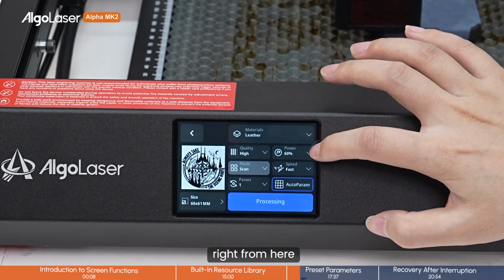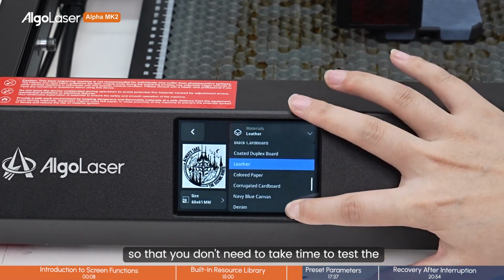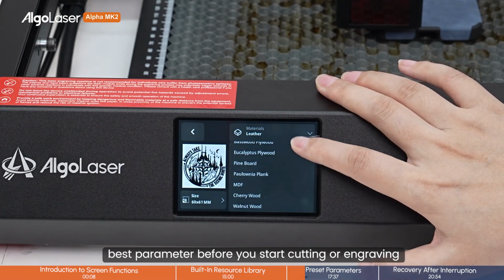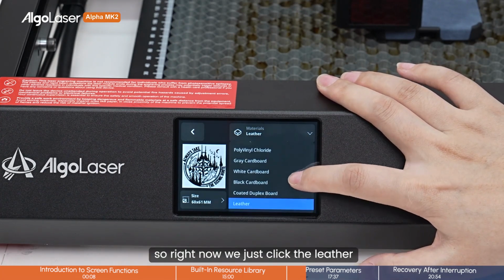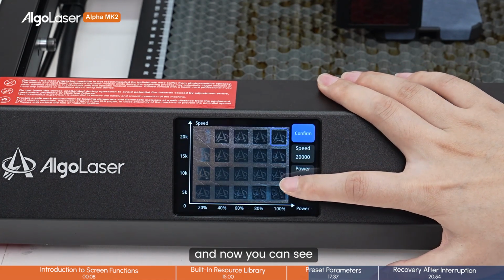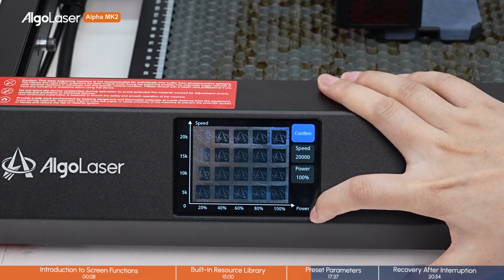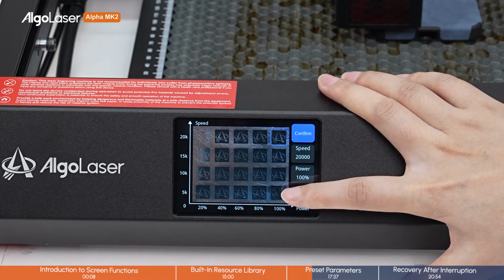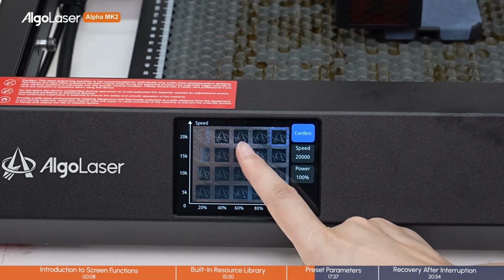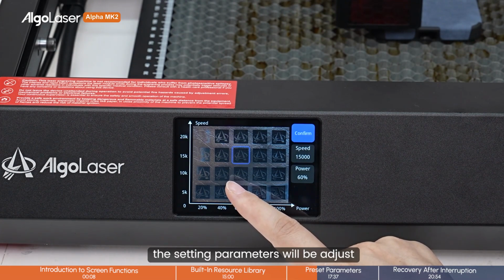From here, you will see so many materials for your option, so you don't need to take time to test the best parameters before you start cutting or engraving. Right now we just click leather, the one we would like to engrave, and now you can see different engraving results for your option. You just click the one that you need. As you can see, once you click a different result on the right side, the setting parameters will be adjusted.